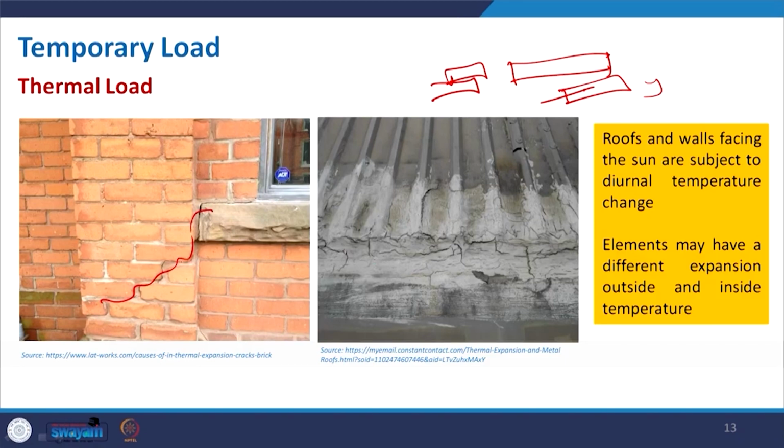This is the brick, and this is roof tin based, and there is some putty which was fixed initially, and due to different expansion with heat, here we see the cracks. The purpose is not fulfilled here, because if it develops cracks, it may also be prone to water leakage, and then your building will get damp.